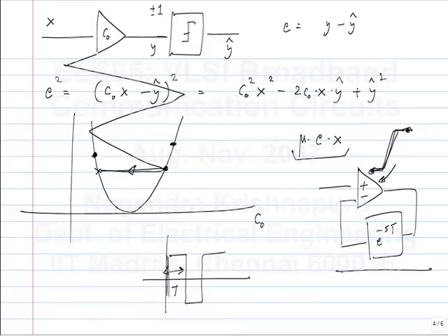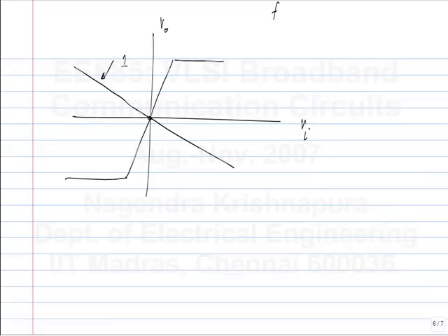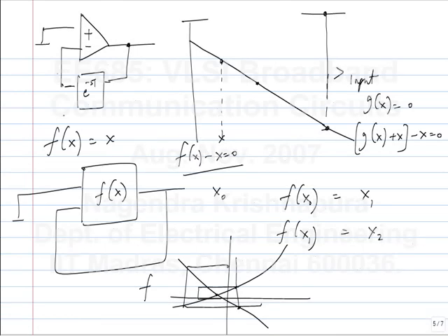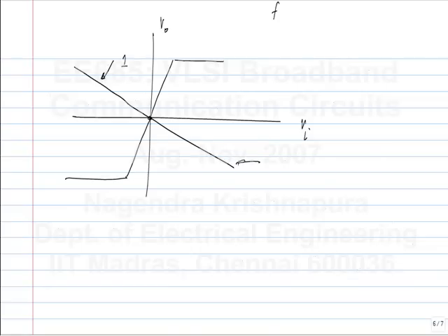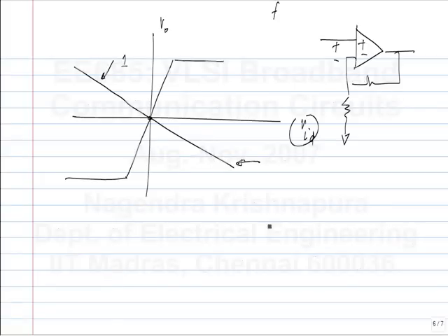So, I guess now it is convincing that if the step size is large, it can oscillate, right? T equal to 0? Yeah, that's correct. I am analyzing this thing with input equal to 0, right? This was 0. This line depends on the input. When I have the standard op-amp analysis, this Vi here is the differential input of the op-amp, not the input to the circuit, okay?